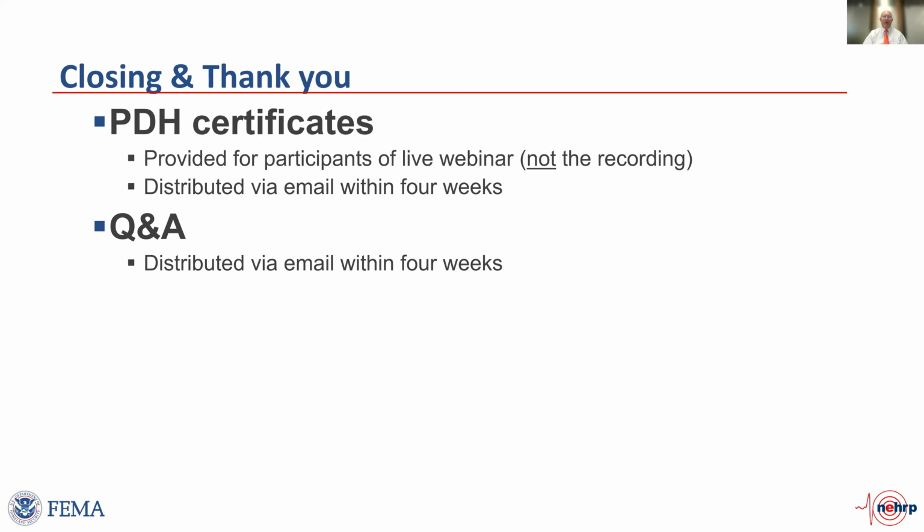Sure. So that one and another one, the triggering dimensions for the diaphragm irregularity were adjusted. And I mentioned this was not the result of lots of reentrant corner diaphragm calculations. Instead, just like the original codification, it was some judgment. I will say that the original metrics that are in ASCE 7-16 and earlier actually trace their origin to ATC 3. So the ATC 3 project.